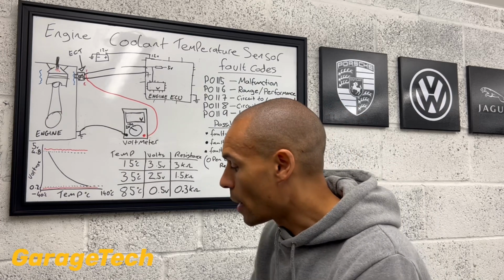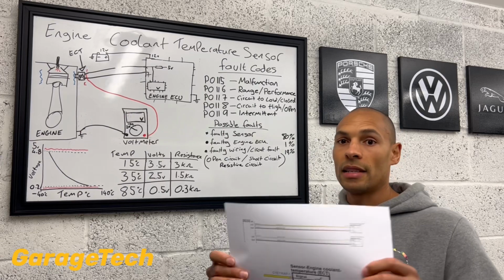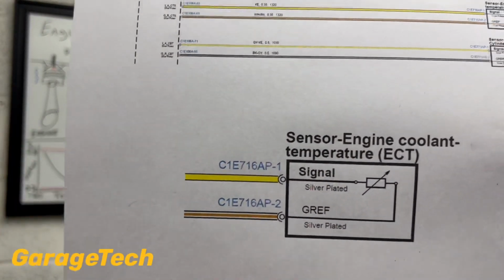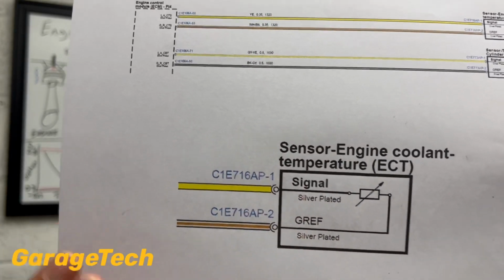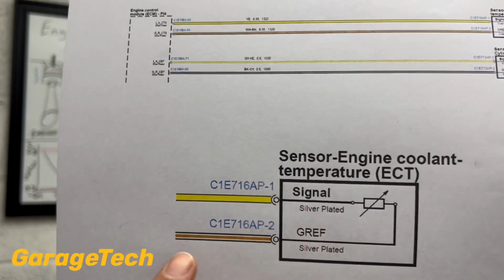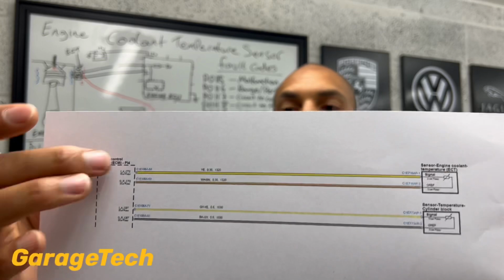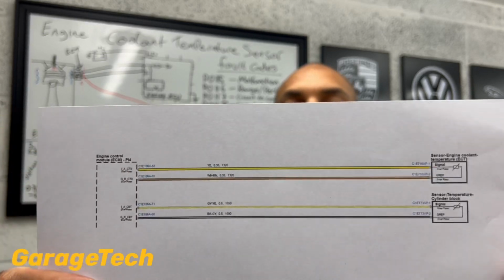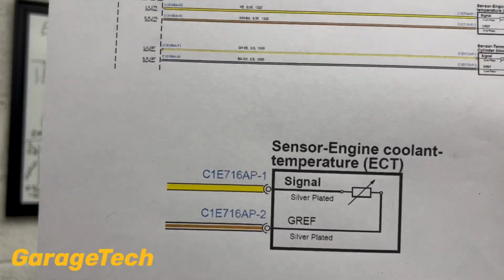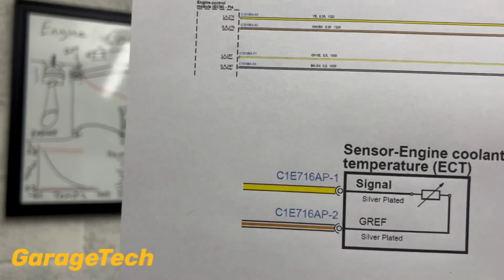Now, if you're not sure about your wires and what's what, I suggest you get yourself a wiring diagram like that, and that way you can have a look at the wires and the pin numbers. You can quite clearly see on here that says signal and that one's ground. So that gives you an indication straight away, and if I zoom out you can see that bit. That's the engine control module, and there's your actual sensor. So if you can get yourself a wiring diagram, it will make things a hell of a lot easier, because then you can see what pins and wires you need to go to straight away.